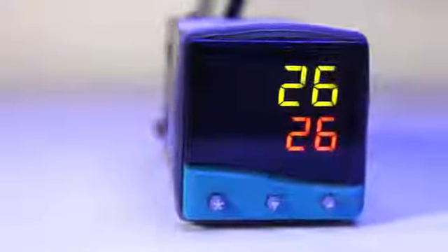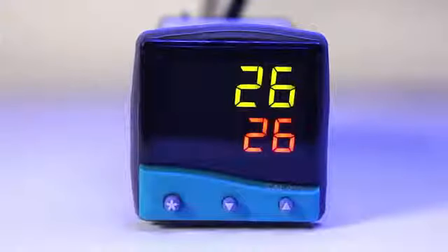It must be remembered that even on products that do not have an adjustable alarm hysteresis, the minimum amount of hysteresis must always be applied to the alarm, and this is usually set at one least significant display digit, so normally 1 degree or 0.1 of a degree.